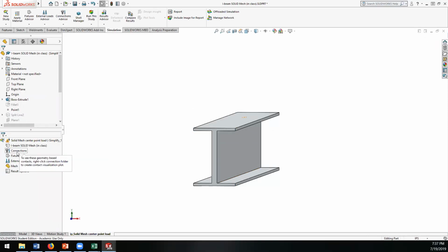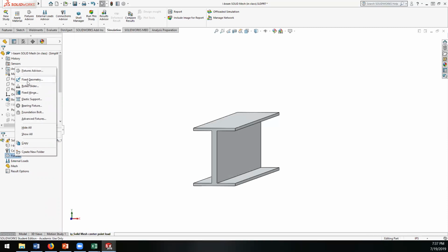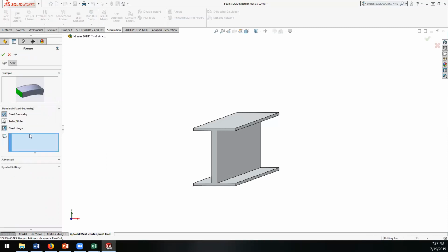So we can do this several ways. I'm just going to pick the bottom edge here and fix it, right? Remember, fixing it is only changing the translations. So it's going to act like a, again, this doesn't mean it's the right way to do this. This is how I'm coming up with it in the moment.